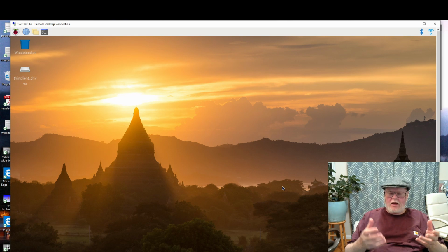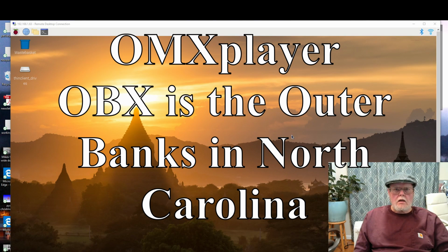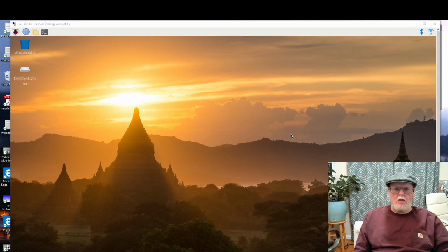And I'm drawing a blank right now as to the name of the video displayer. It's something like OBX or something. So I just checked, and that player is OMXplayer that I need to install. Now, OMXplayer itself is already installed in the Raspbian software, but there is a piece of connective tissue needed to hook it up to Python that is not installed, so I'll have to install that. And I also need to install FEH.